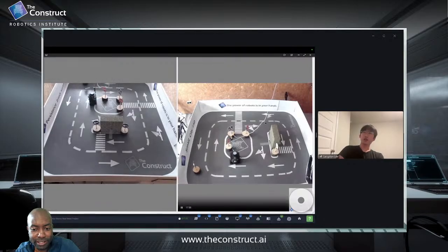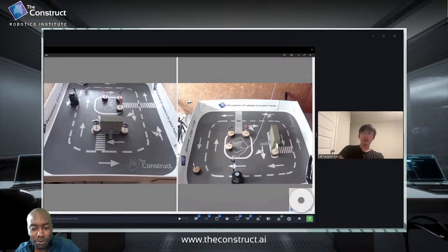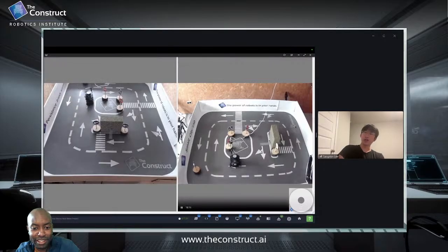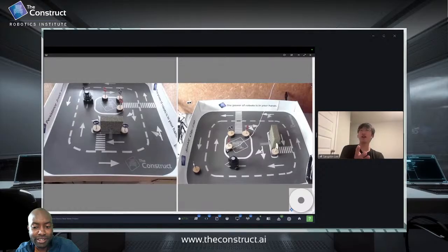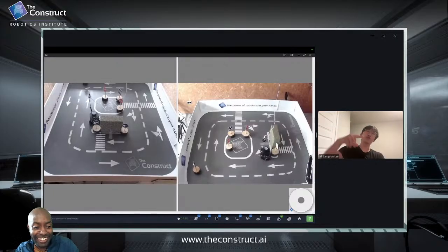So when it went backward? Yes, that place, around almost where your pointer is. It's because for my cases, as long as it's not close to the threshold, it'll go straight and it'll turn. But the robot could be at different angles, so you can't really have one case to say turn this angle at this point. Based on the angle of the robot's current position, it might turn differently, and sometimes it turns twice. I was just being lazy, so I didn't want the robot to turn twice. I just wanted the robot to go back once and then turn, so we have more space in the front.